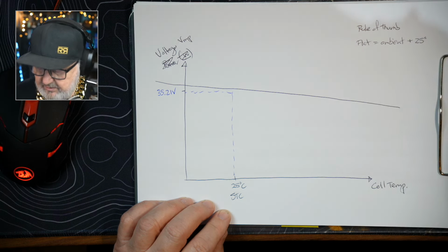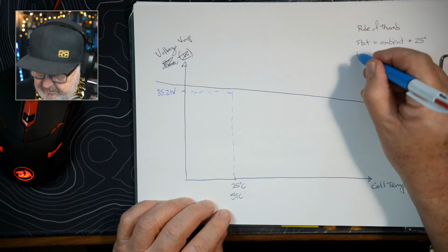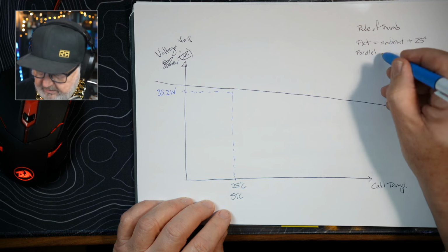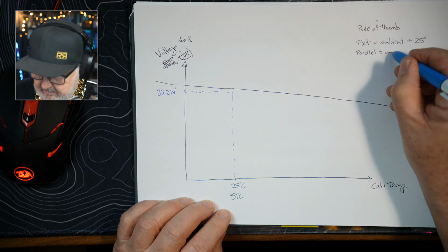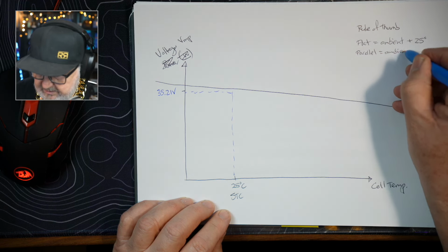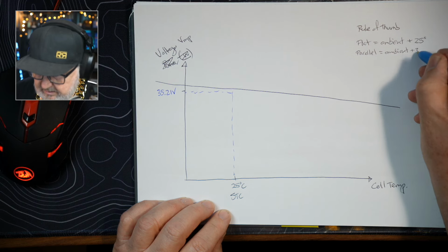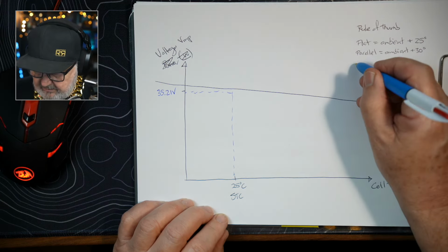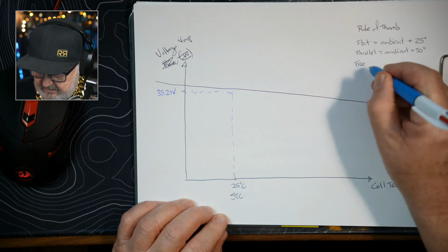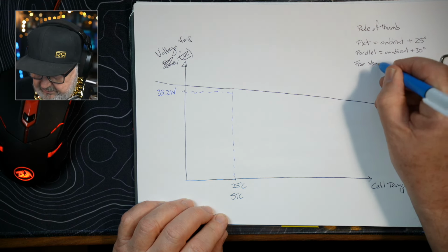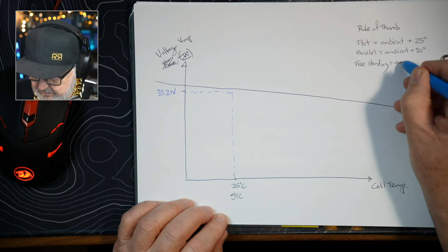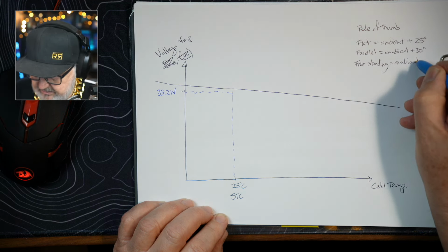So they'll be 25 degrees hotter. If they're parallel to the roof and there's a bit of slope on the roof, you'll get some passive cooling, i.e. you'll get air movement behind the modules. And if it's freestanding, like on a tilt frame, you'll get the optimum amount of passive cooling from any breeze as well as convection.